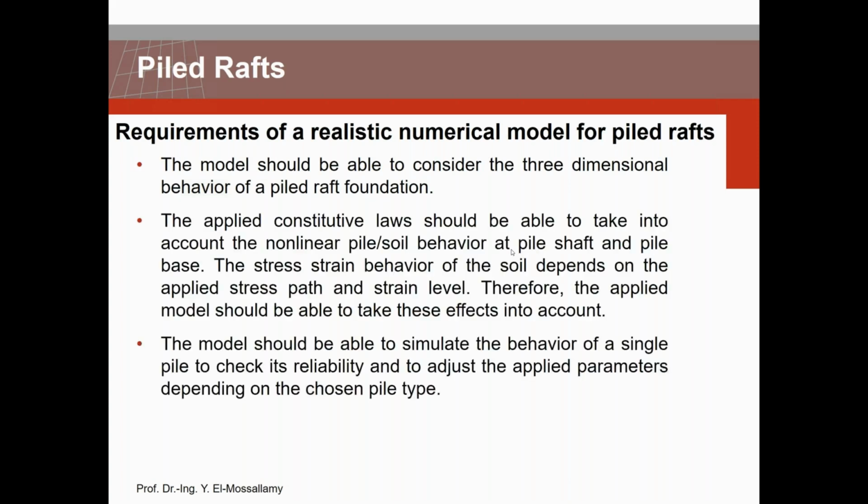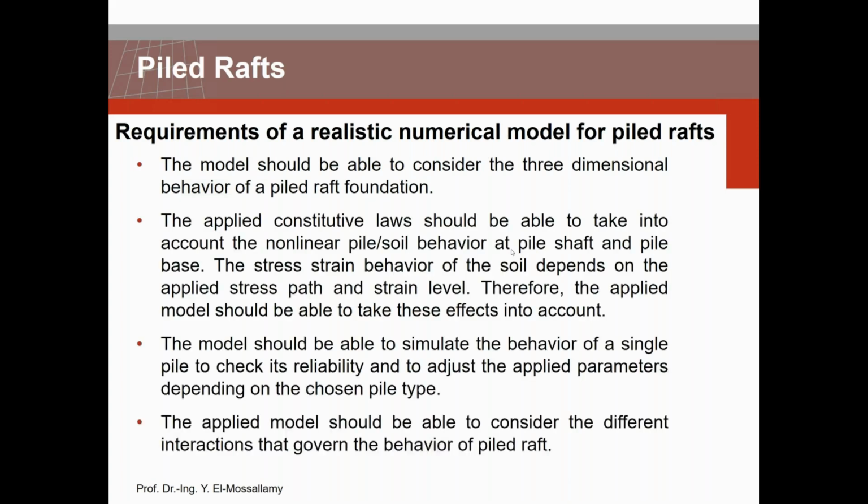The requirements for a realistic numerical model. The model should be able to consider the three-dimensional behavior of a pile raft foundation. The applied constitutive laws should be able to take into account the nonlinear pile-soil behavior at pile shaft and pile base. The stress-strain behavior of the soil depends on the applied stress path and strain level.